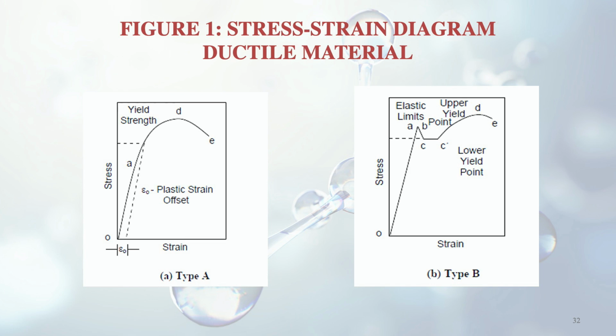After that, still elasticity is there up to a certain point, like you can see with the curved line, that it is representing elasticity, meaning the specimen after being loaded, when the load is removed, will come back to its original position without any residual strain. But as soon as that point is crossed, meaning the limit of elasticity is crossed, then the yield point comes in, where plasticity begins. So after that, if you unload, then residual strain will remain.